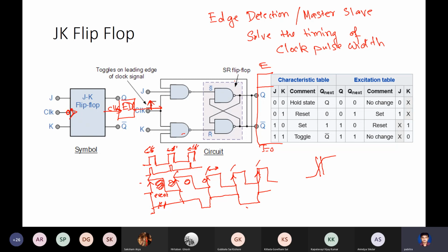So you take the truth table, all possible combinations of inputs and the current state Q, and on them just apply this logic to find out what Qt plus 1 should be. The important part of this logic is that there is a feedback loop.